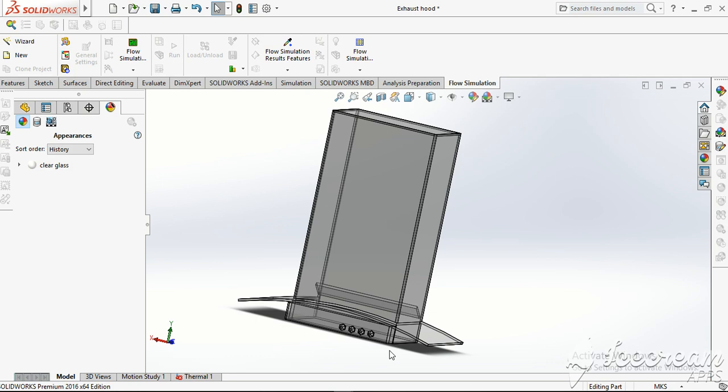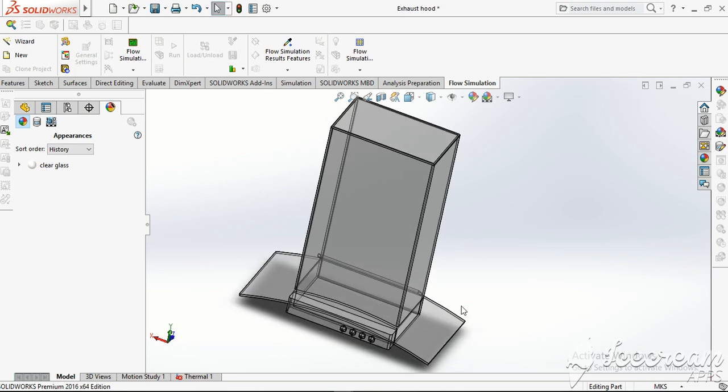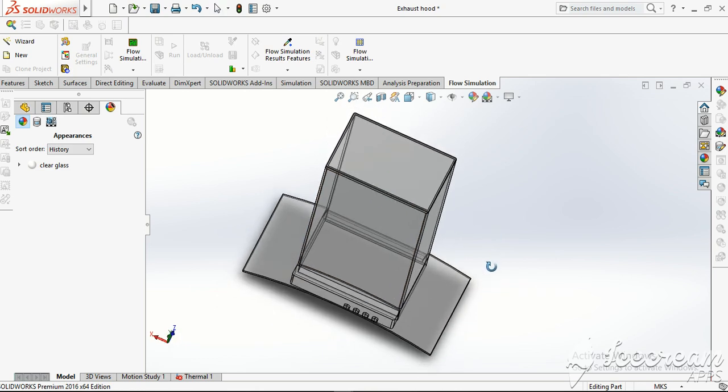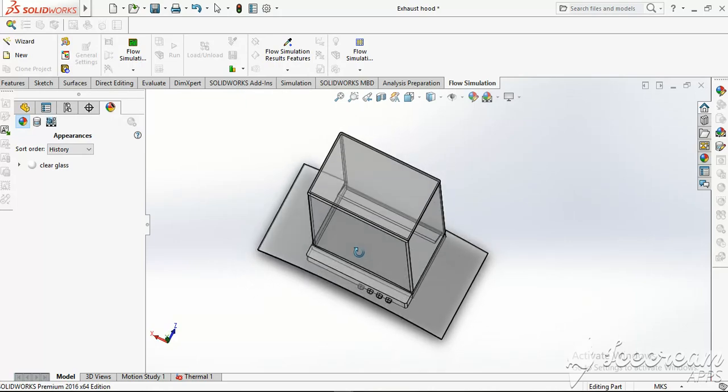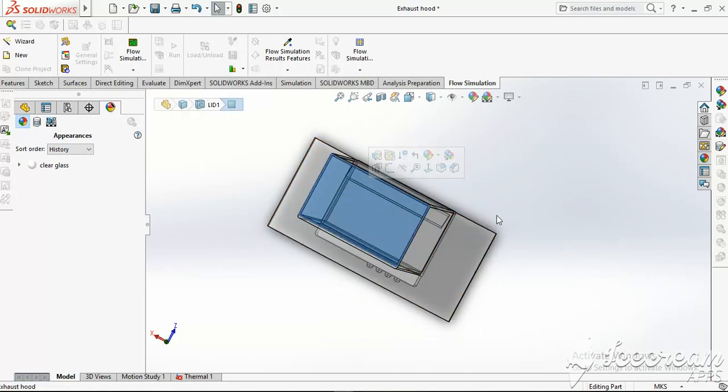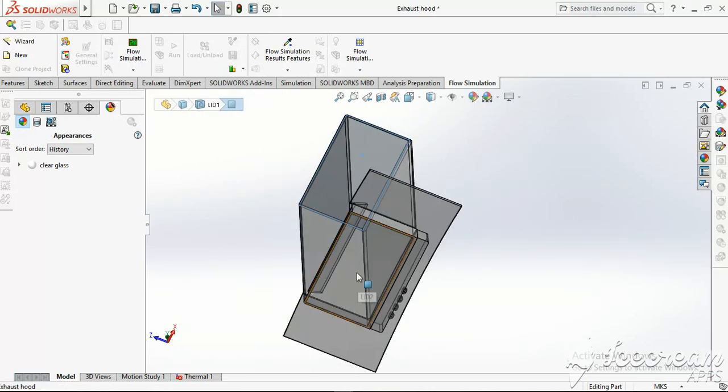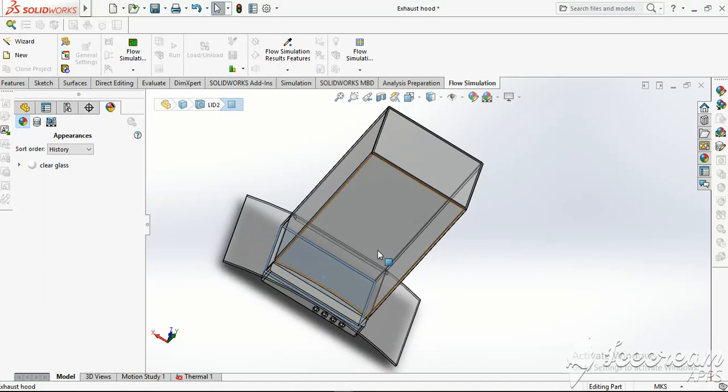Everyone, and today we'll be seeing a quick tutorial on how to do fluid flow simulation for the internal flow on SolidWorks. So basically, if I have created this duct and I want to analyze the fluid flow inside it, obviously there will be no closing here and at the end, but SolidWorks demands that you must have inlet and outlet closed using lids.